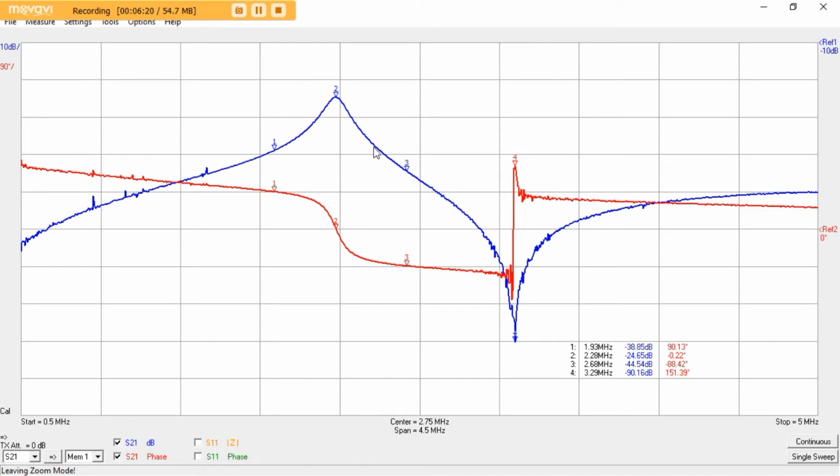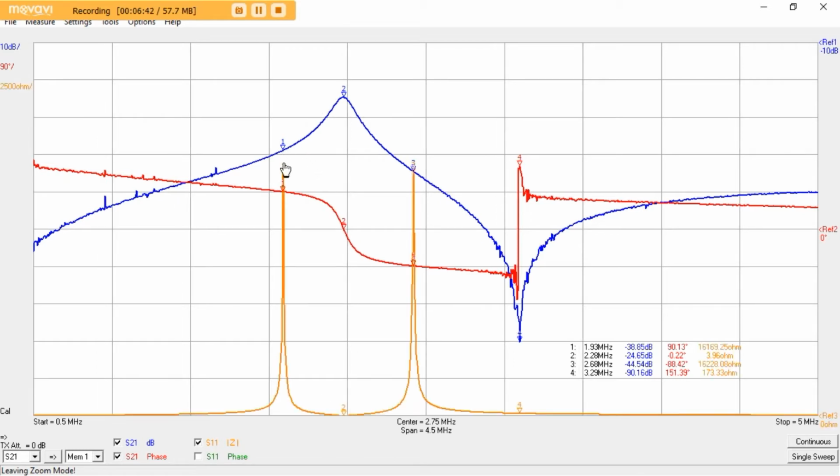Now, also we noticed, and we've gone into this before in other posts, that the Tesla coil is more complex than just a single series resonator. It has other modes in here. We've talked a lot about the parallel modes that come about, and we see that again in S21.